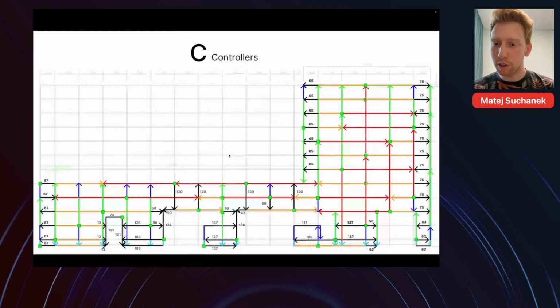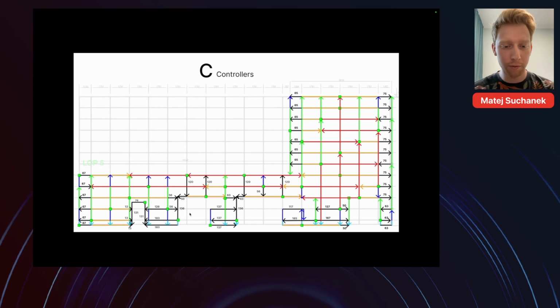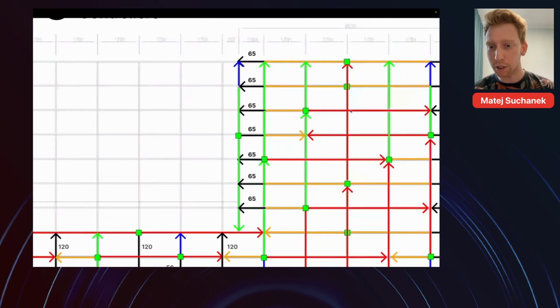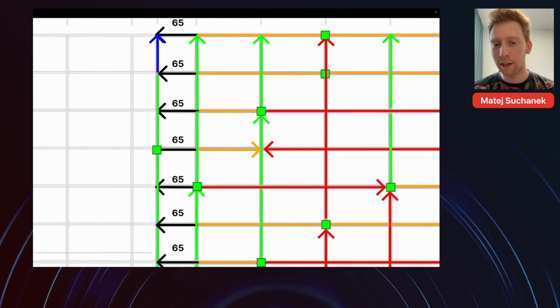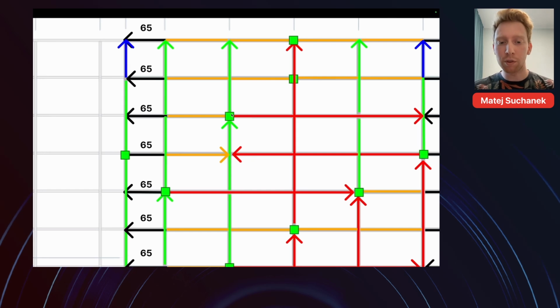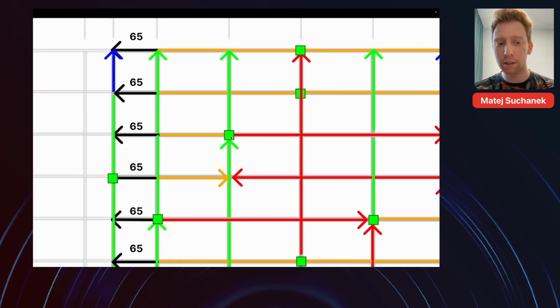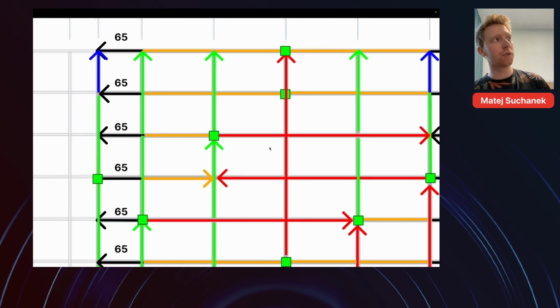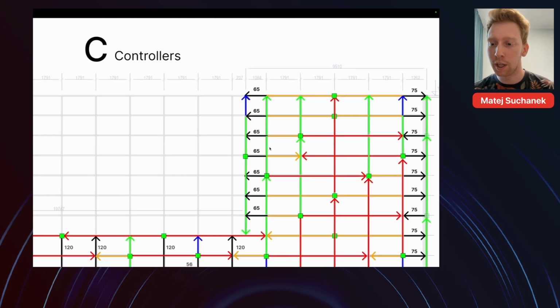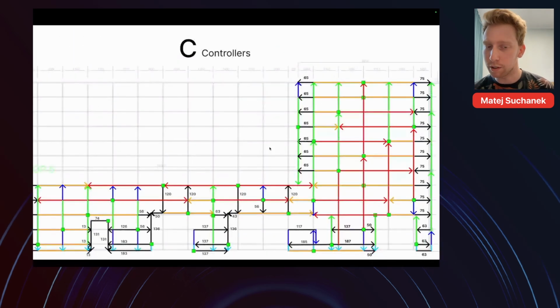The only difference is that you have controllers on the facade that do not control DALI lights with simple dimming. Every controller has connected addressable LED strips, and each controller then not only controls the intensity of the brightness as in the sports hall, but also generates animations.